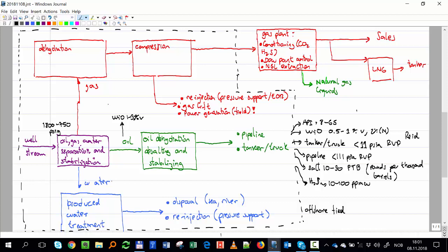Water, this water that I have here coming from the separator, normally has a number between 500 and 1,000 ppm, and I think this is on weight. This is oil in water. So it has that amount of oil that I cannot separate with a normal big vessel separator, so I have to use treatment. We're going to see the equipment now. We have different options.